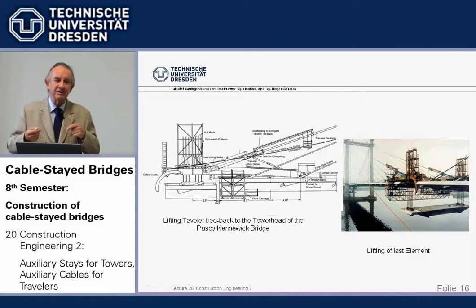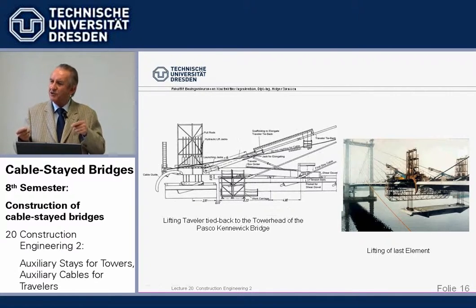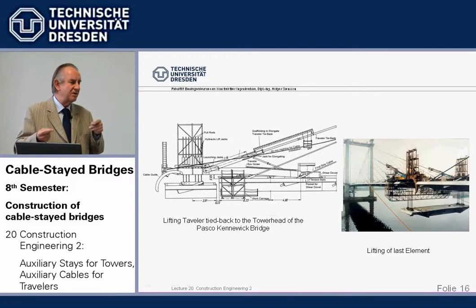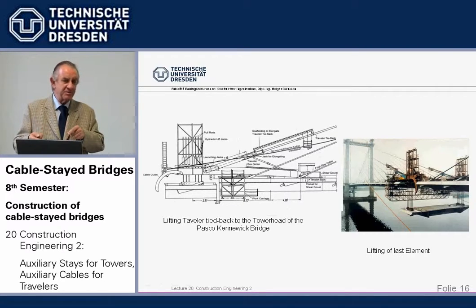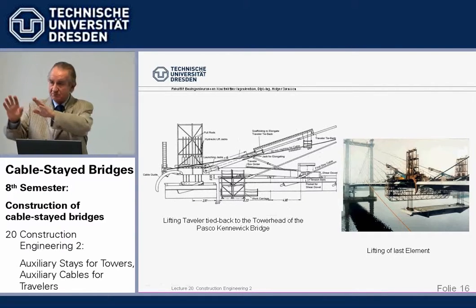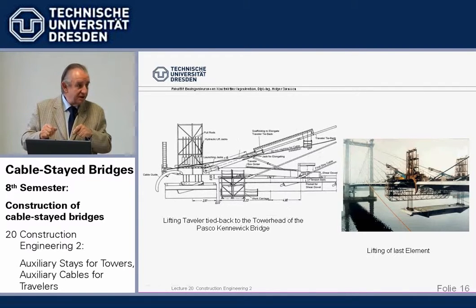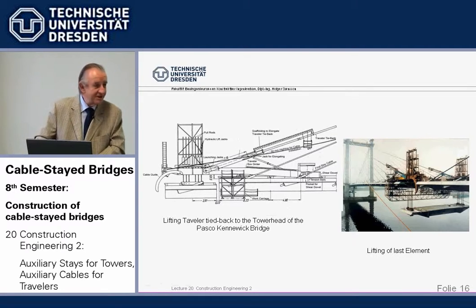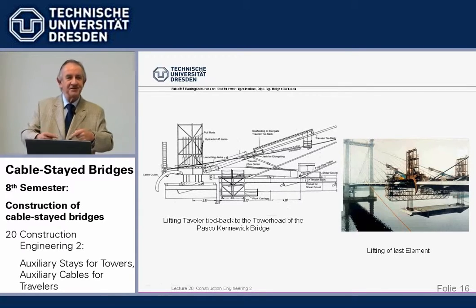But with our bridges we have always put one optional construction method on the drawings and have said, for this construction method we have checked the beam system and additional quantities required for that are included. That's a big thing for a contractor. Now, if you, contractor, choose something different, up to you, but then you are responsible for additional quantities. And that makes him think twice always. So very often your system comes.